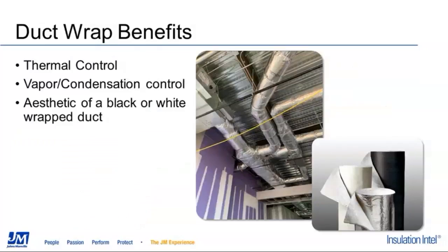The duct wrap benefits. When we look at duct wrap, the purpose for the insulation is different. Designers should consider using duct wrap insulation when acoustics are not a priority. Let me reiterate that, when acoustics are not a priority. Duct wrap offers an excellent thermal control, and the facing can help control the condensation. And JM even offers our new black and white face duct wrap insulation that can be used as a design element, but duct wrap should not be used in applications where acoustical control is a requirement.